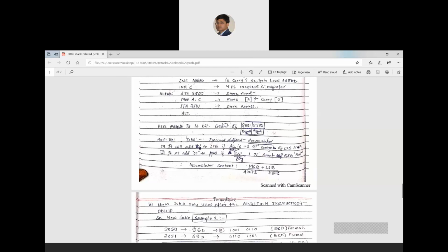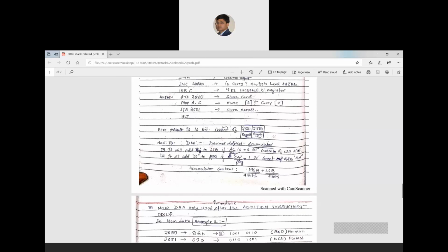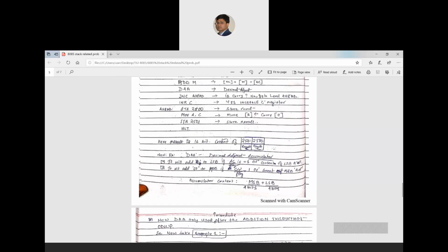So if you can see in the LSB part that this is not in the range of A to F, but you see the auxiliary carry is 1 in the previous step, that means in the addition step. So in that case also you have to add 06 to these lower 4 bits, and similar to that the upper one also. So you have already added the accumulator with the memory location value, so you may get a carry in that addition.